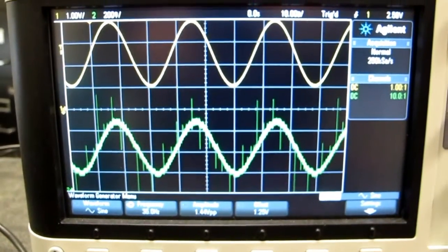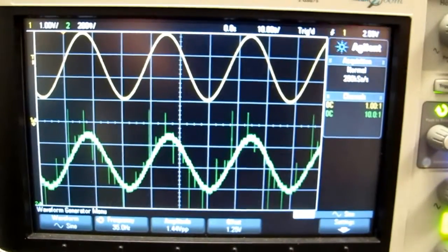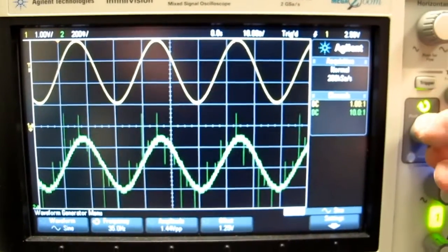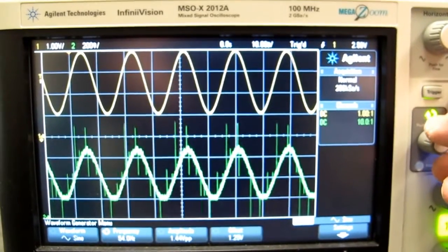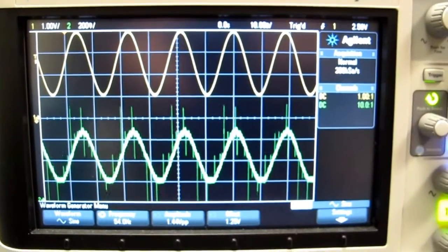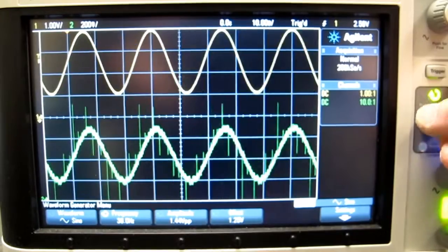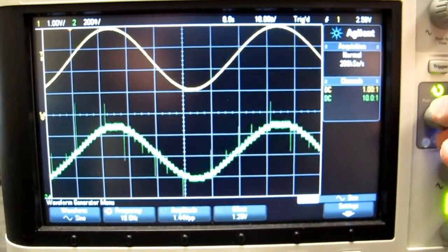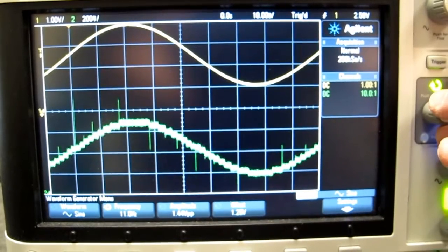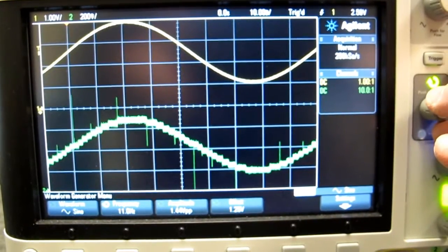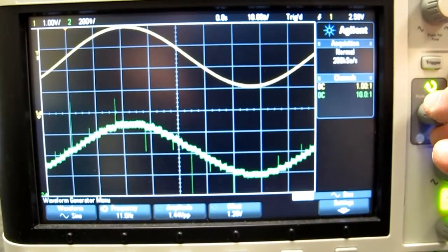This is a very simple DSP low-pass filter implemented, and I'm going to change the frequency, and you can see really the input and output are tracking each other. You notice the steps in the output on the bottom there, the quantization levels. If I spread it out, you can see them a little bit more clearly. That's again because of the only 5-bit D to A converter, but that's good because it shows some of the real issues of A to Ds.